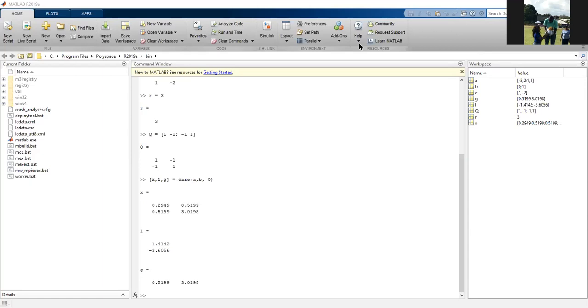And that new matrix L, you see the two gains are negative. So therefore, because it's negative, we know that that system is stable. So it stabilizes the system, and you have the gains that you would use to get the minimum energy for the stability of the system.